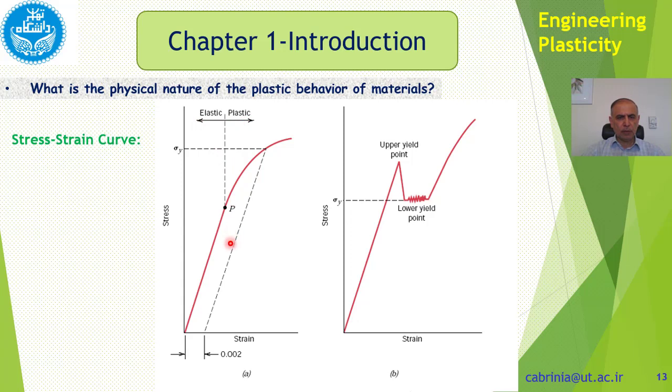Elastic deformation is a linear behavior, and plastic deformation is nonlinear deformation. Elastic deformation is recoverable, plastic deformation is not recoverable. Plastic deformation is a permanent deformation, elastic deformation is not permanent and could be recovered upon removing the load.